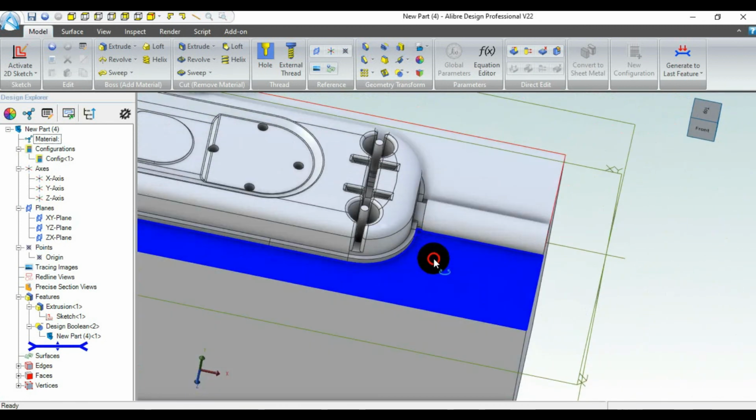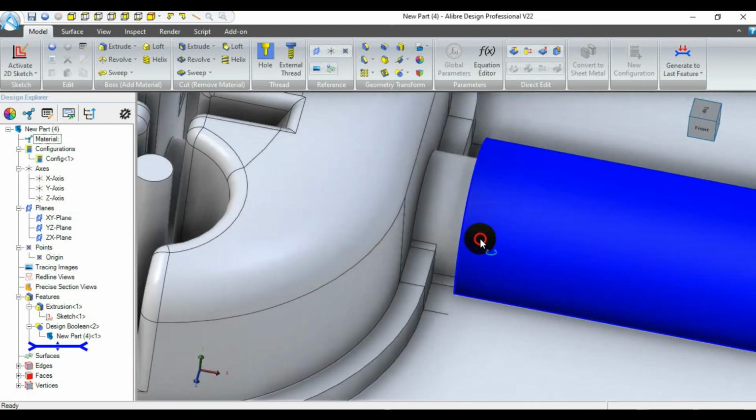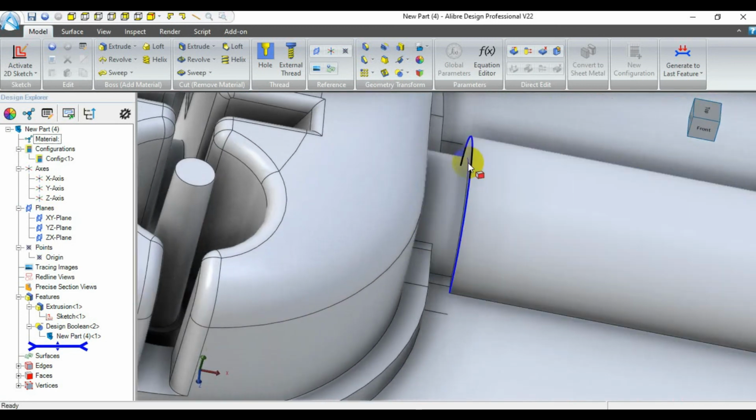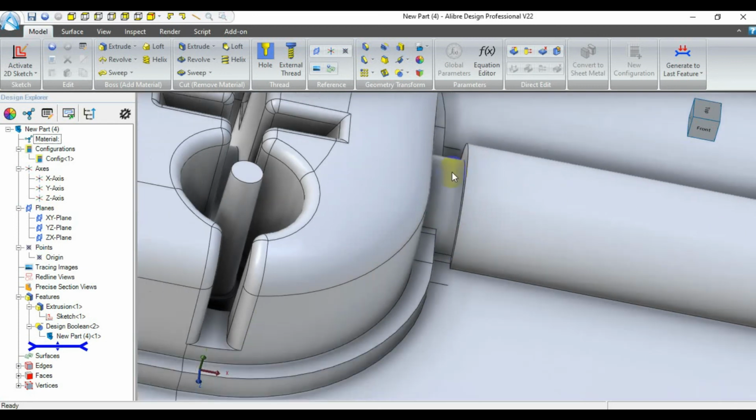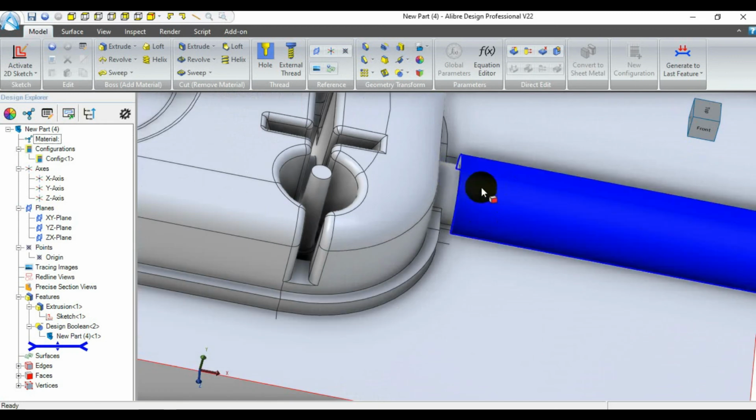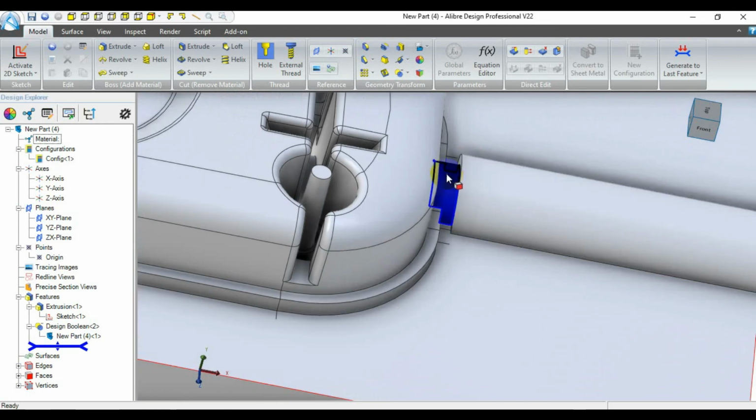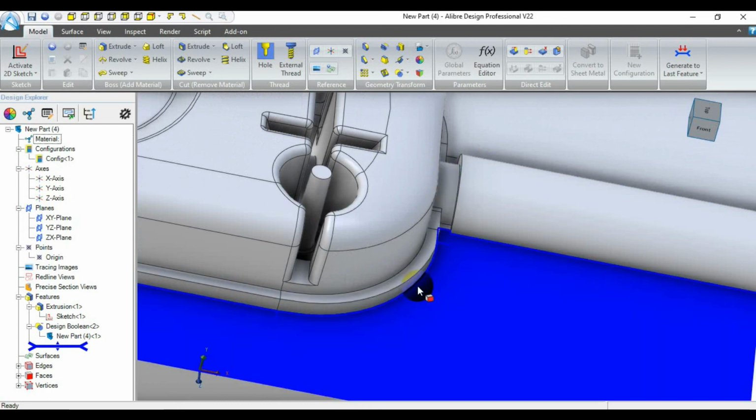Now there is a little bit of an issue with the reverse draft on this particular face here, on that face there, but it's not a consequential thing. It's not going to interfere with this here in any way, shape or form. The draft will go the opposite way, but on such a small area it's not noticeable in the part, and that's just general practice to make a wider shut face area and then localize EDM this particular area here. And so there you have it.